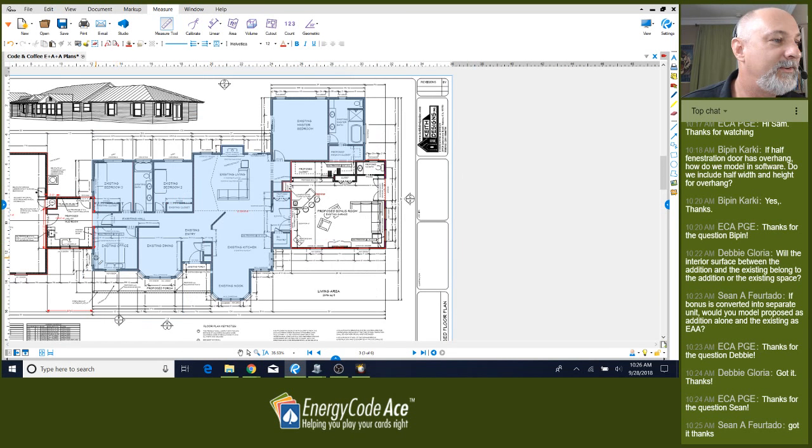We need our interior wall. And this, I'm just going to take a linear dimension because interior walls are not subject to orientation, right? Let's call this a perimeter dimension. So what we do here is we can just add up all this wall length, multiply it times our ceiling height.